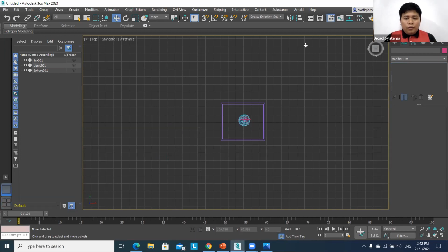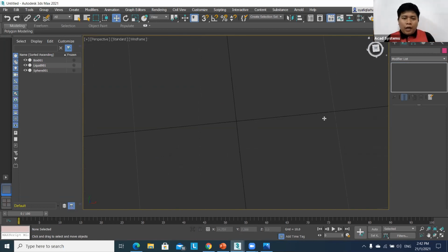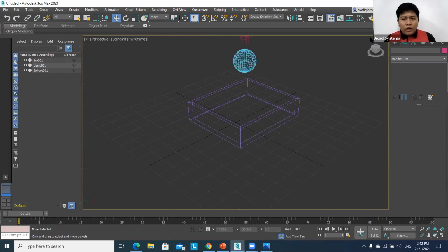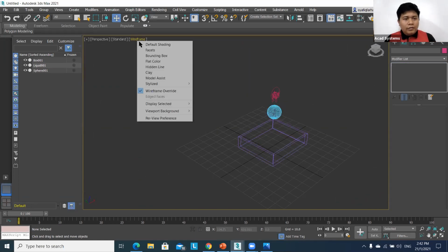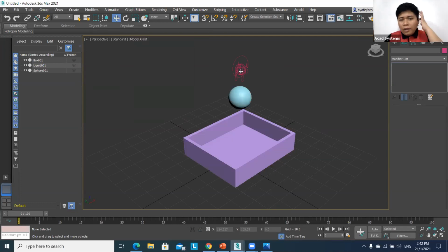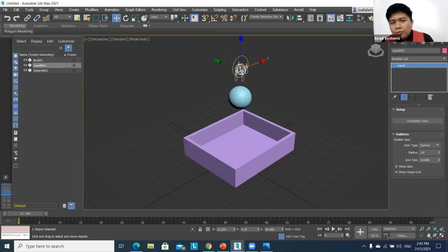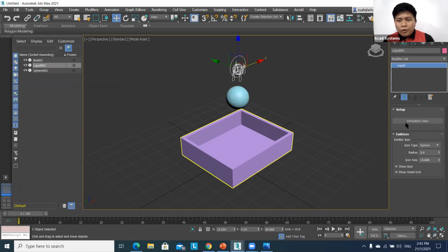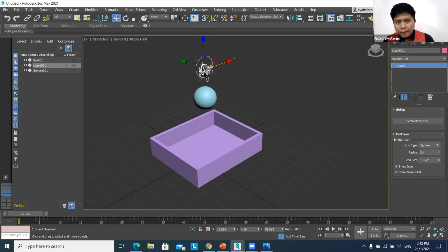Right, so the view cube, I believe, has the same function as in other software. You can click on the home button and change this area to asset, model asset. And now we want to make the fluid start to move, to animate. To start animating or simulating your fluid, you need to click on this fluid, again, modify and set up over here.